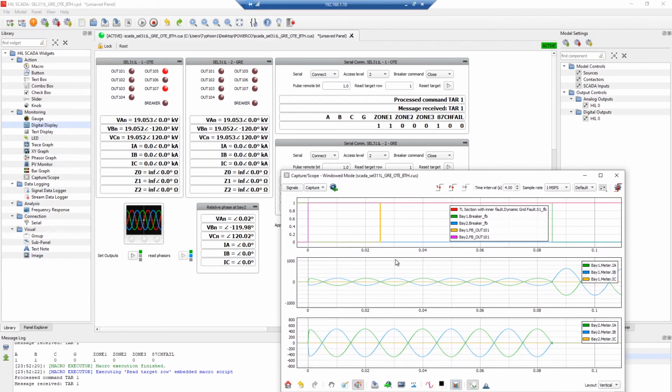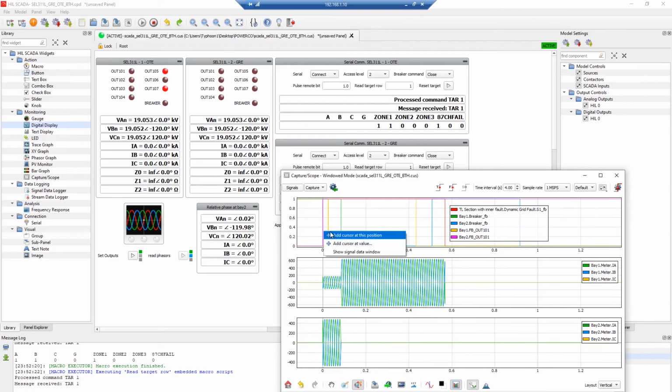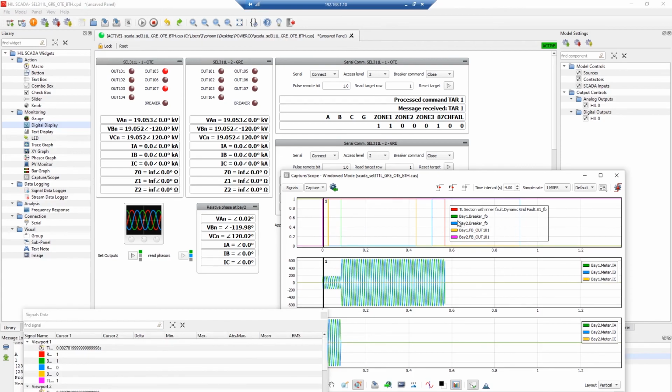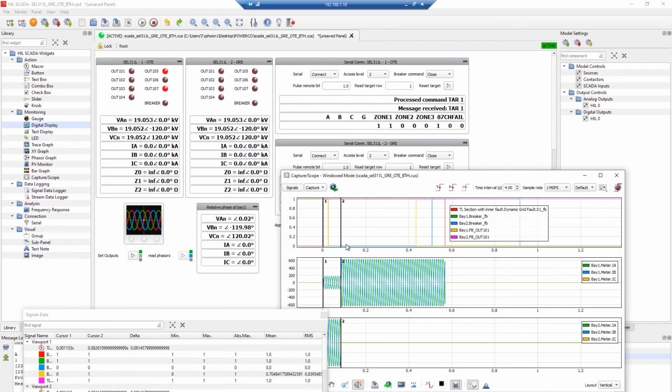We can see here the operation around 8... what is that? I'm again confusing my units here, but let's put this so this is the first strip right there. So that's our 84 milliseconds, but relay on bay 1 operating with a zone 2, it actually took almost 570 milliseconds to trip.